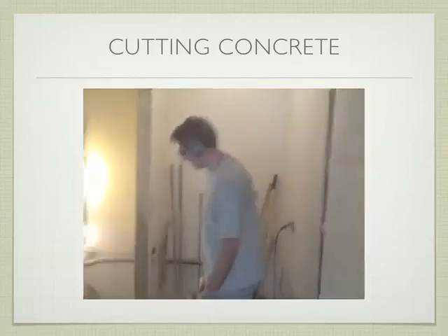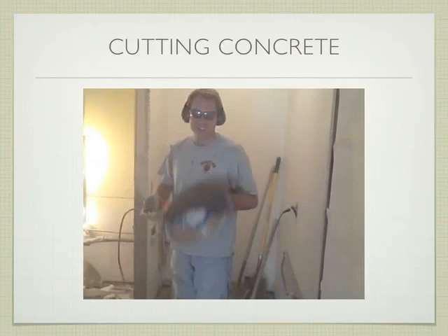So after you do that particular piece, then you have to take a sledgehammer, break out that piece of concrete, remove that, dig down your 4 feet, and tie into the new sewer line. Obviously, you have to have the inspector come out and verify that you tied it in correctly and you glued it in correctly and all that kind of stuff. After that, you backfill around your pipes. Then you drill into the sides that you just cut and removed.